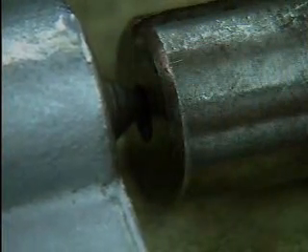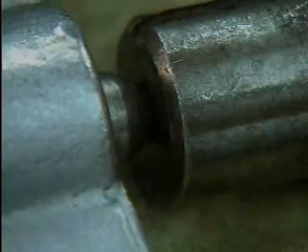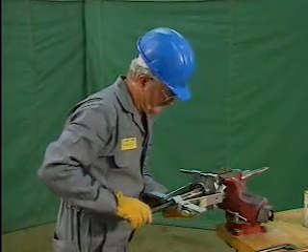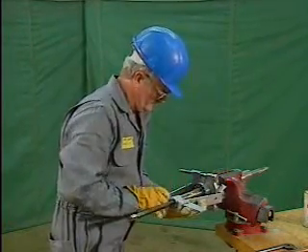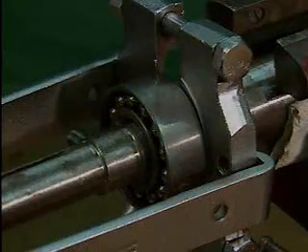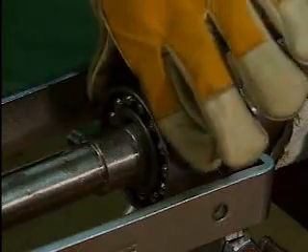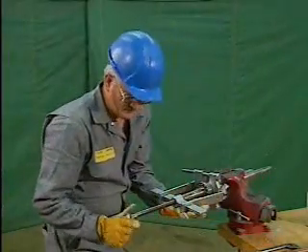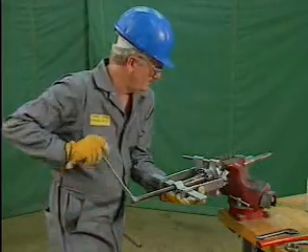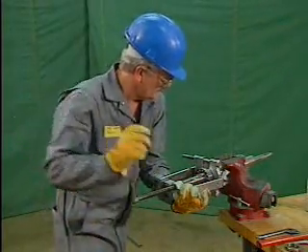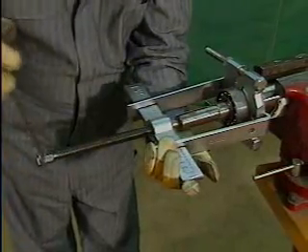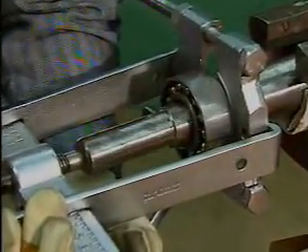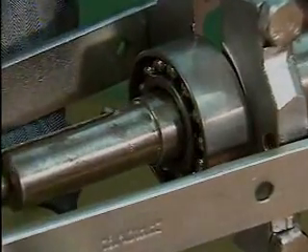In this example, the mechanic places the lead screw into an alignment hole in the shaft. Then he tightens the lead screw. He checks the position of the jaws to make sure that they will only push against the inner ring. A good way to check the jaw position is to tighten the puller and then turn the bearing's outer ring. If the outer race can move freely, then the jaws are positioned correctly. Next, the mechanic uses a wrench to tighten the lead screw and draw the bearing off the shaft. He is careful not to cock the bearing. If the bearing is cocked as it comes off the shaft, it will jam and the puller will have to be readjusted. The mechanic continues pulling until the bearing is loose enough to be removed by hand.